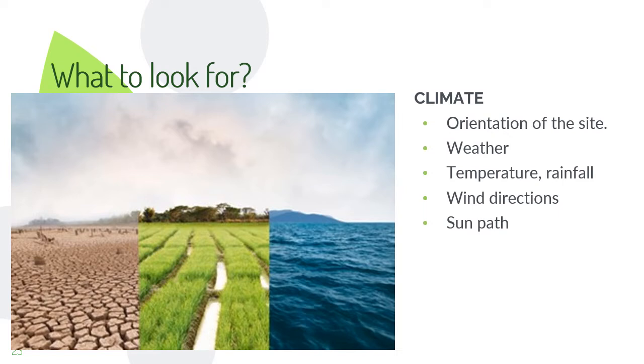If there's any rubble on the site, it could suggest there has been a previous development or possibly landfill on the site. Many of these site issues, particularly services, would be picked up on a topographical survey or other professional report. But for the benefit of a student site analysis assignment, I think it would be good to demonstrate that you have considered the hazards that could be on or around the site.